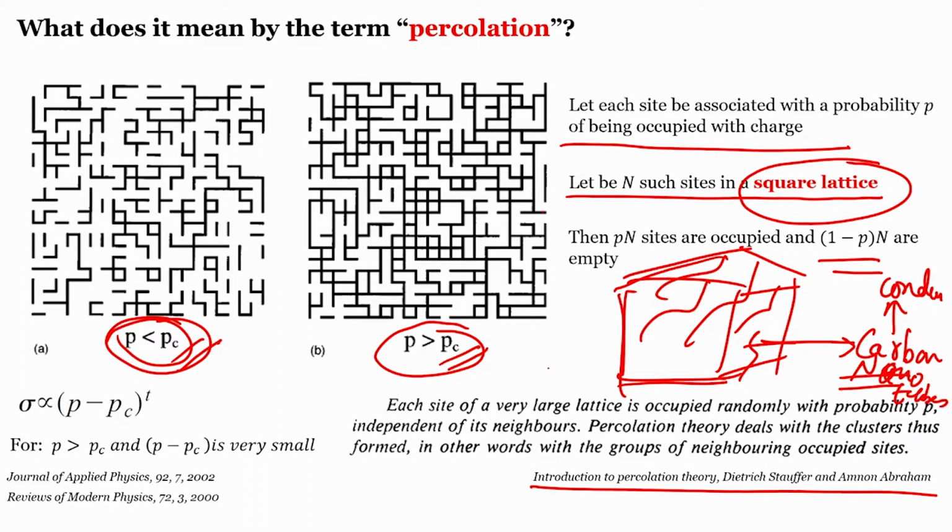And this holds till a particular fraction is reached, which is Pc. So let us say I am taking 1 gram of polymer and I am putting 0.01 gram of CNT, and if this particular volume fraction corresponds to something which is less than Pc, then in this polymer composite, if I apply current, there won't be a continuous path. I won't be reading any potential at a voltmeter if I put one here.